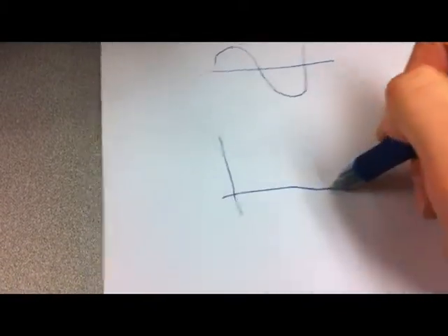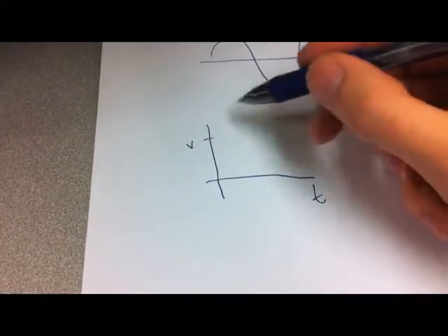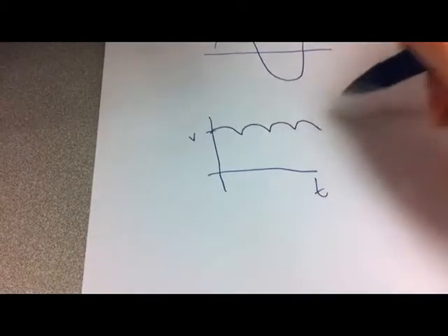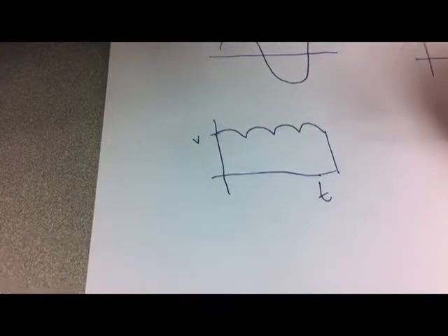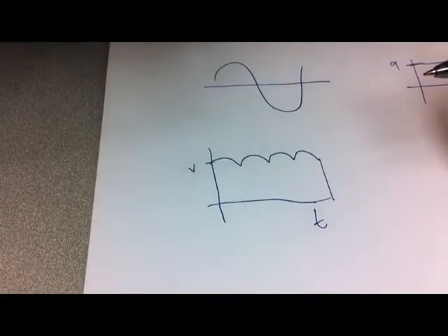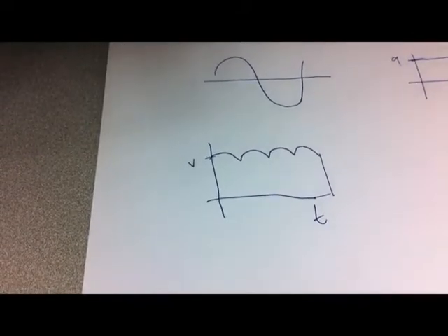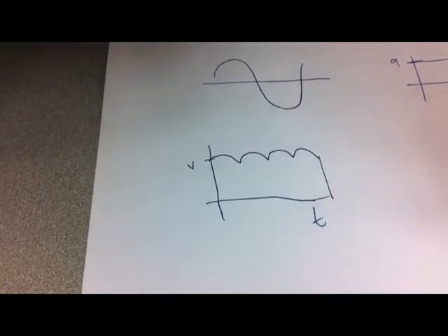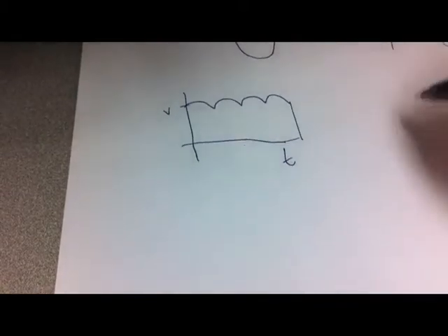How this works is over time, the voltage will have small ripples in it. This is due to the AC artifacts called harmonics. AC voltage is changing during time, but the bridge rectifier tries to nullify that change and keep it positive always. So we will construct a bridge rectifier using 4 diodes.